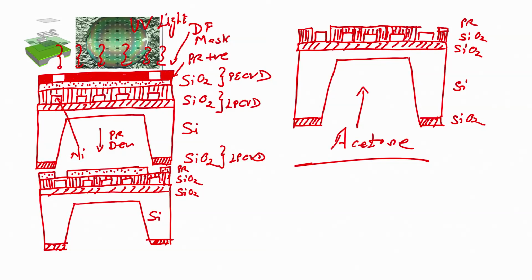Right. Photoresist will be stripped off. So, now what you have is silicon dioxide protecting your micro heater, right, except in the contact area. So, now if we apply power or voltage here, because of the resistance of the heater, current will flow and the heater will heat up.